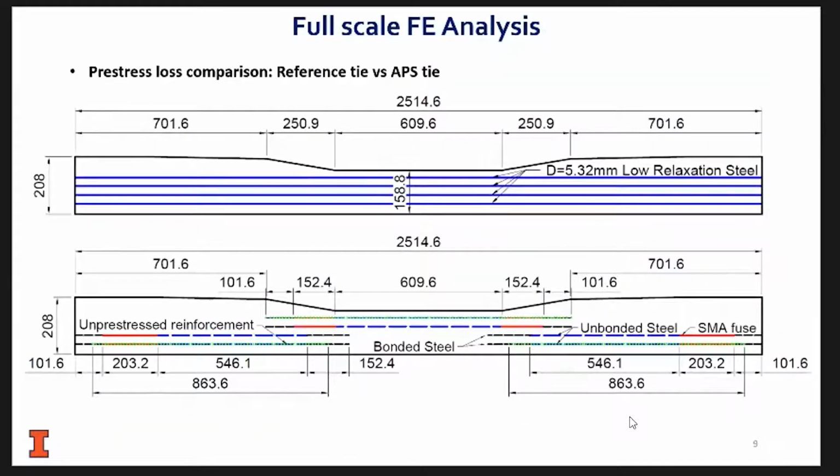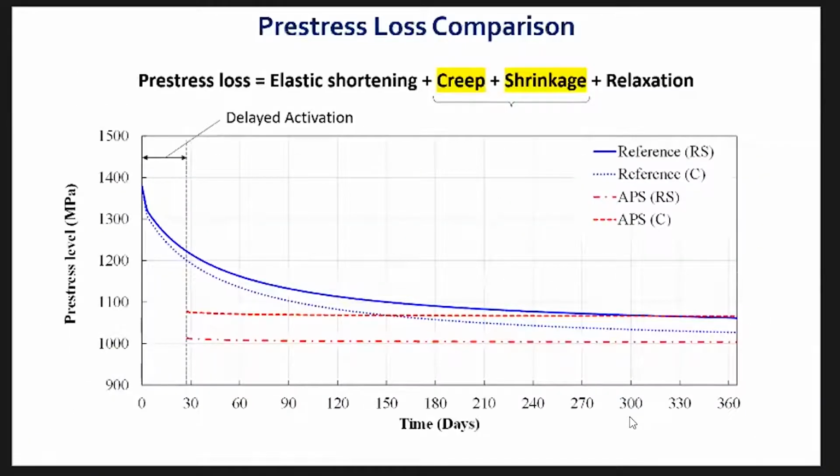Now, after phase 1 was completed, we wanted to think a little bit bigger, full scale now. Let's just take this to the full scale. So at the top, drawing here, you see this is a conventional design. At the bottom, this is what we started thinking about. What if we just eliminate all the steel and just put the pre-stressing where it's needed, as you can see here. But one thing that came to mind is pre-stress losses. Something that's very important. We cannot overlook pre-stress losses when we're dealing with pre-stressed concrete. It was going to happen no matter what.